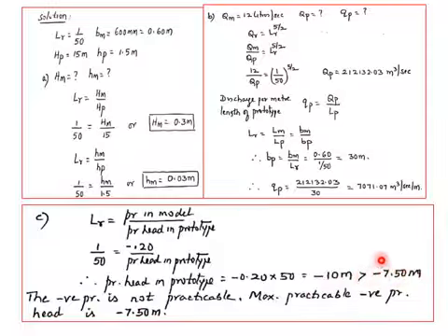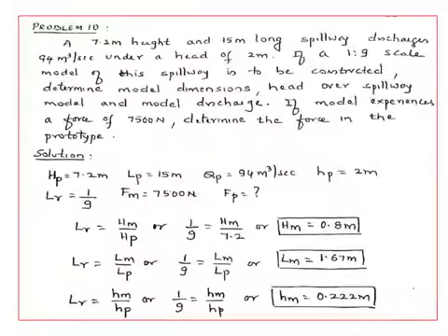So vaporization of water molecules takes place, converting into vapor bubbles, and these will be carried to high pressure regions where they collapse, creating a very high dynamic pressure, which may form cavities on the surfaces, or which may damage the surface. That's the reason why this negative pressure is not practicable and not allowed.